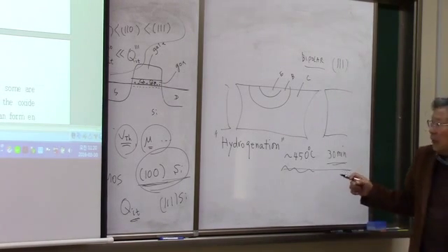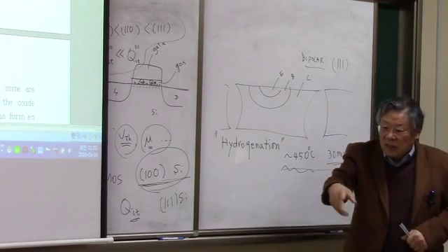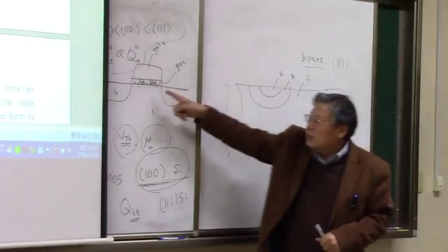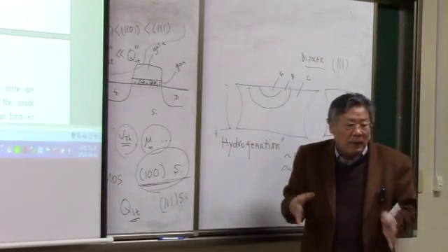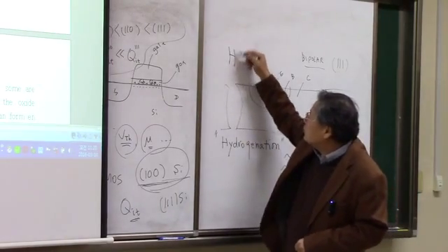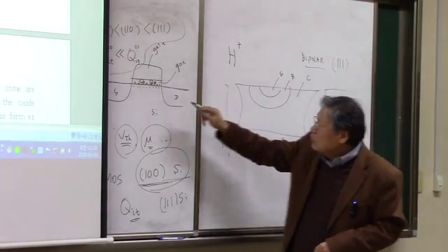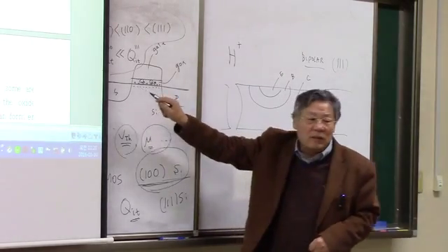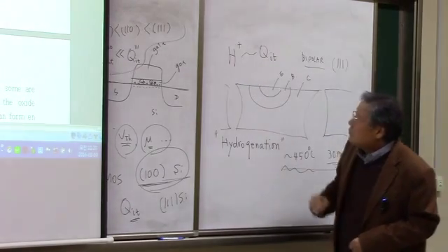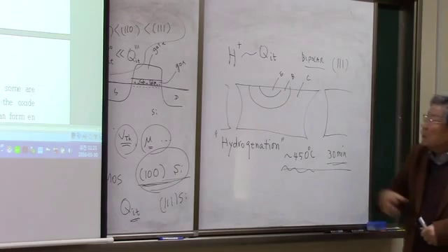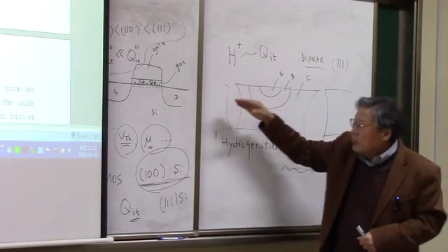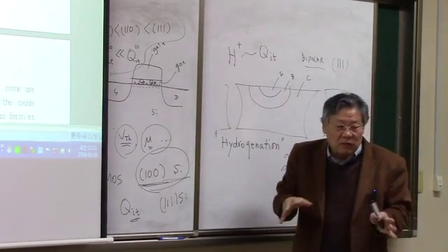for 30 minutes. And then we're going to see later in the masking properties, the hydrogen can penetrate this oxide very easily. Hydrogen is very mobile. So hydrogen, which is H plus, a proton, is going to annihilate these negatively charged interface trap charges, okay? It compensates or annihilates the interface trap charges so that you can decrease them.